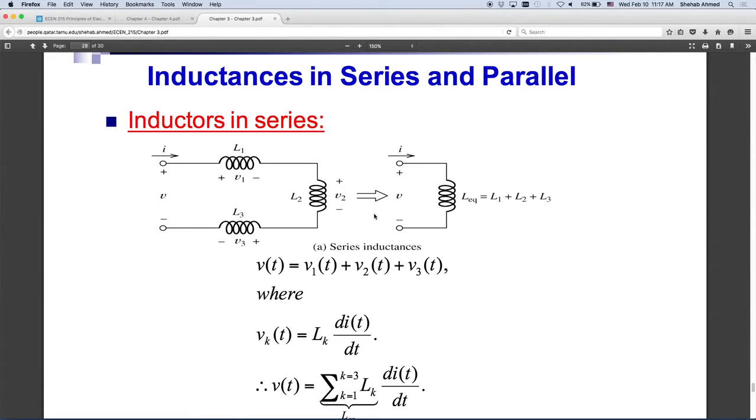This voltage will be the sum of the voltage across each of these individual turns in the inductor. So there is a voltage difference between the actual turns in the inductor, so you have to insulate the wires of the inductor. It's not bare copper, it's insulated turns. If you have a very high voltage and you want to put insulation around this material, you need space. So sometimes you just cannot build one big inductor; you maybe have to divide it up into different smaller inductors.